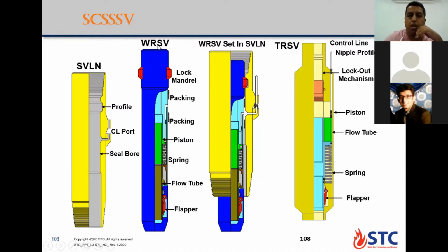the wireline safety valve, and you close it again, and you start to control from the surface by control line. When you pull the wireline safety valve, you need to close it first, and after that you pull out from the hole. This is the usual procedure for running in open position and pulling in closed position.